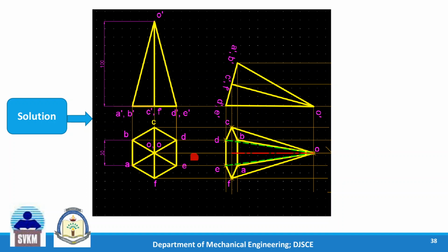It means that it is resting on this triangular surface on HP now, and we take the projections down, and we take the horizontal projections here, and we complete this top view in the second step. So we have solved up to this in the previous two sessions. The wordings were different because they were phrased such that the solution would be achieved, and now we have changed the wording a little bit more, so that now the axis is also inclined to VP.